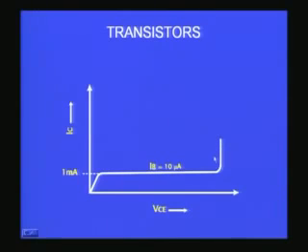Then it will become perhaps spoilt, because a large current flowing will produce large heat, and that may damage the transistor. So, we should not go into this region, but you would find the graph looks with a small linear region and then almost a flat constant collector current. That is what you get for a given 10 microampere.